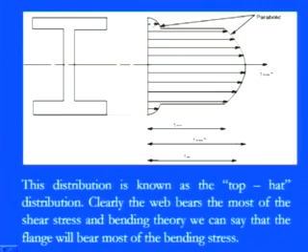However, if we want a concrete analysis, and write the expression for the shear stresses for the flanges and the web separately, we will have this type of variation. We have some variation in the flanges, but the real variation with the maximum value of the shear stresses is in the web portion only. The distribution in the flanges is of this nature on both sides. Since the square terms come in tau minimum and tau maximum, obviously the parabolic distributions are there.